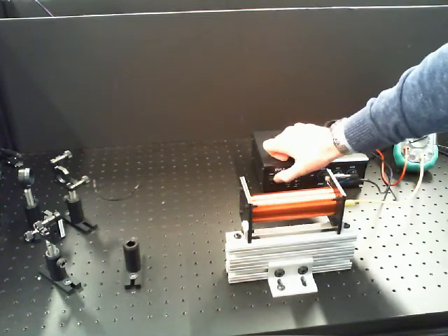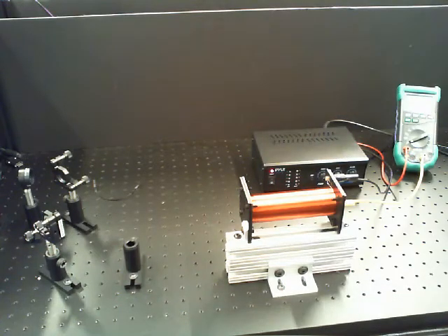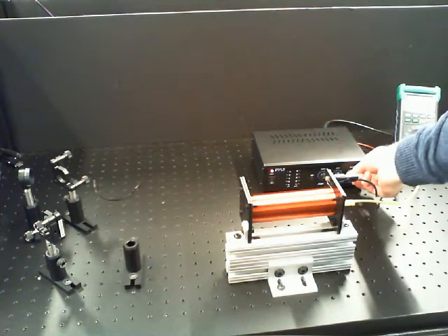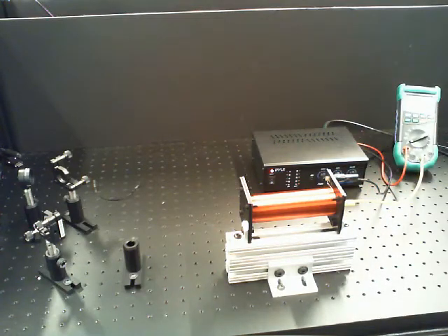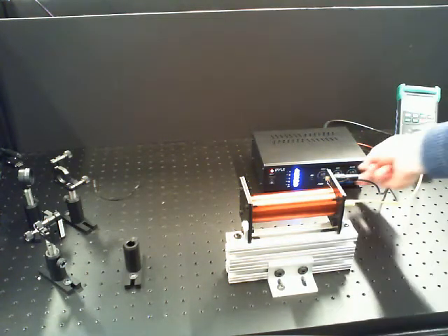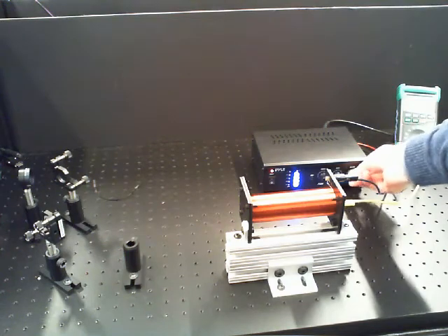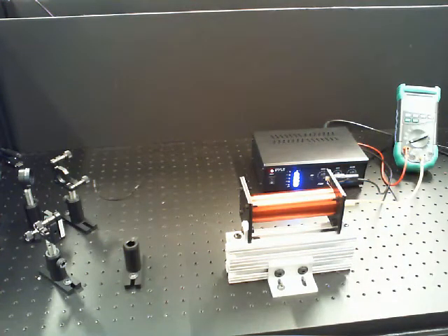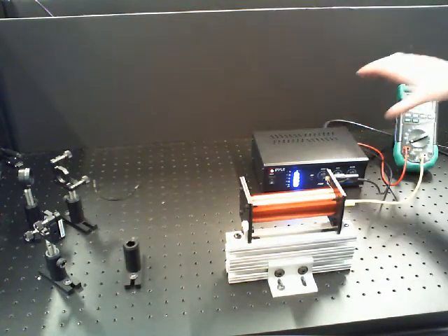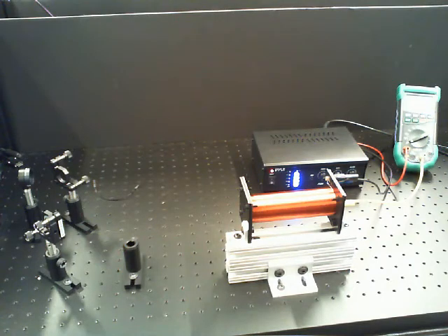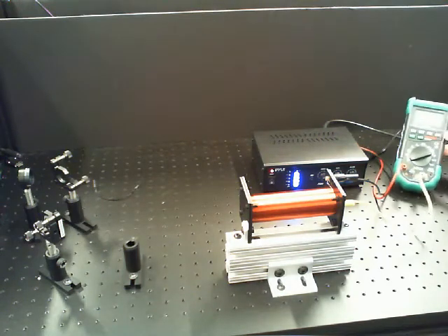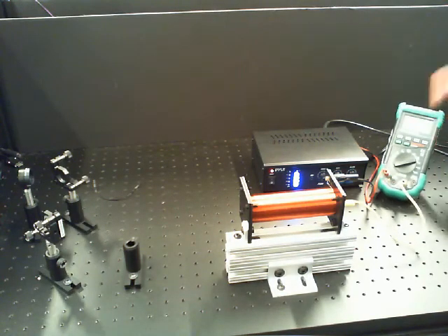So it will be controlled by a power switch on the front, and as detailed in the lab manual, you'll just increase the volume knob. And as you increase it, you see these blue LED lights increase. And what we want to do is set up for 1 amp worth of current going through the solenoid so that we can understand how much magnetic field we have running here. And so to do that, we'll be monitoring the AC current using our digital multimeter.